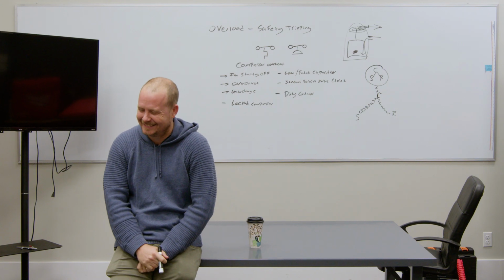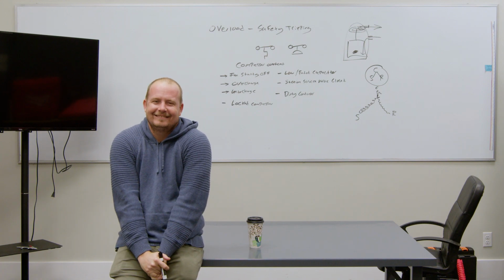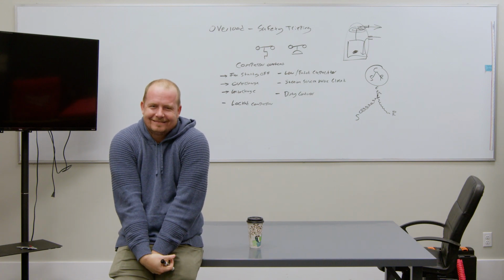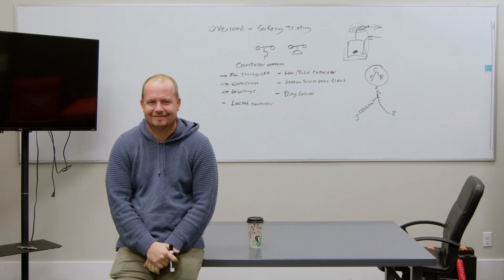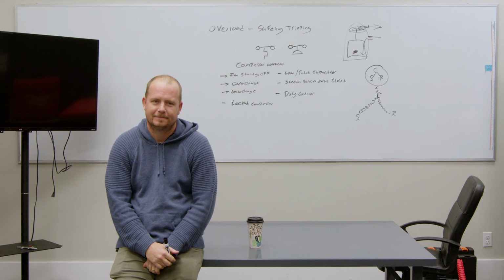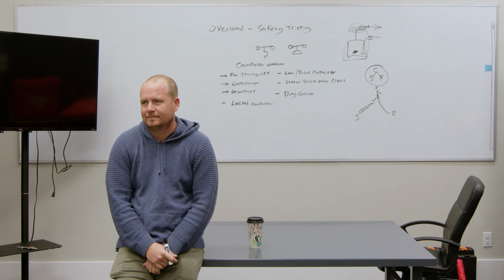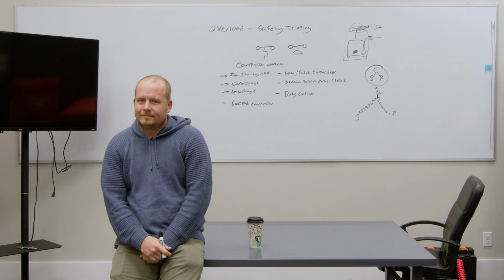So when you're thinking about this potential issue, are you thinking that the ice getting on the... There's no ice outside. Right, there's no ice outside. No, the ice getting on the TXV. My guess is that's what's slamming down. That's my guess, because there's just such a low volume on the suction. It's not unusual to have a frozen system and a warm suction.